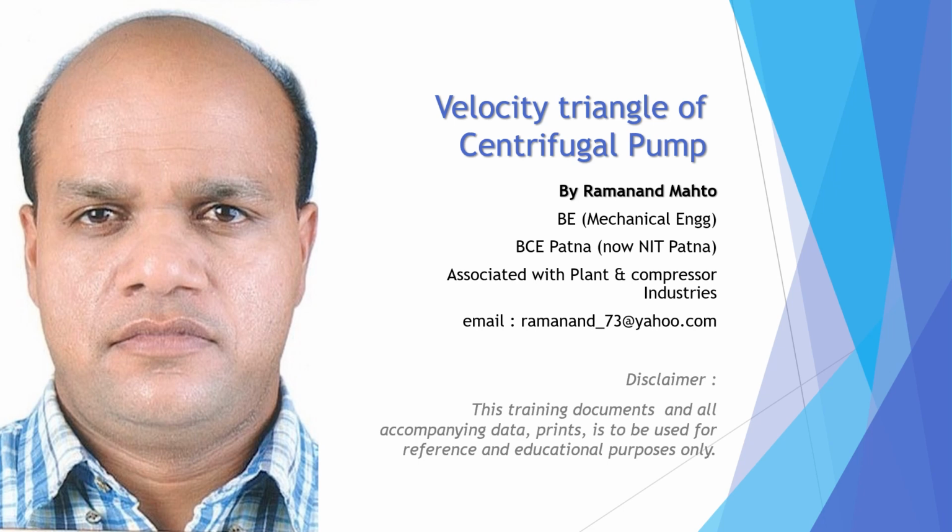In centrifugal pump, slip factor or slip phenomena occurs at impeller outlet, and so there will be two outlet velocity triangles, one for ideal case without consideration of slip factor and another for real or actual case with consideration of the slip factor. Velocity triangle for ideal case is shown as dotted lines, whereas actual case is shown as solid lines.